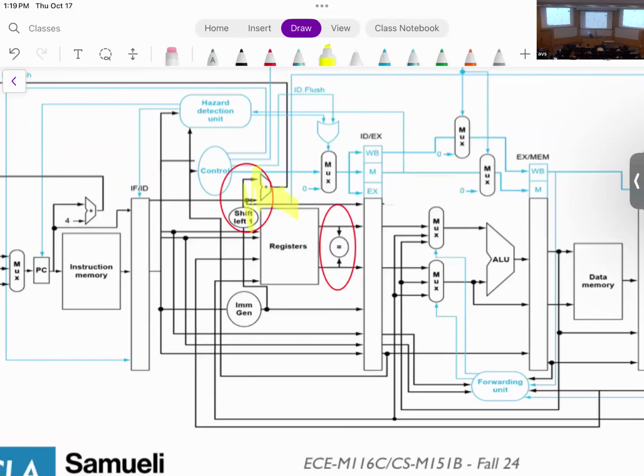So the first thing I'm going to do is move that adder, which used to be here, to here, so that I can immediately generate this value. Of course, that means the critical path here is going to be extended, so I have to be careful about that. But thankfully, since the memory is longer, I can move this here. So that's the first thing I'm going to do.